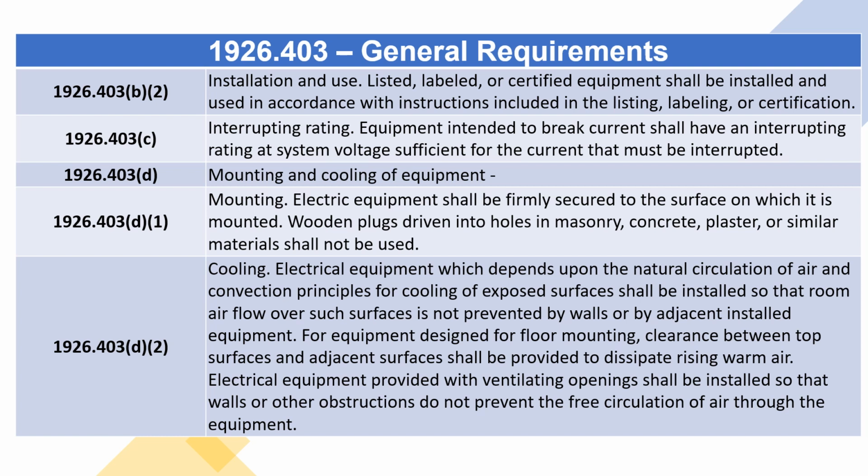1926.403(D), Mounting and cooling of equipment. 1926.403(D)(1), Mounting. Electric equipment shall be firmly secured to the surface on which it is mounted. Wooden plugs driven into holes in masonry, concrete, plaster, or similar materials shall not be used.